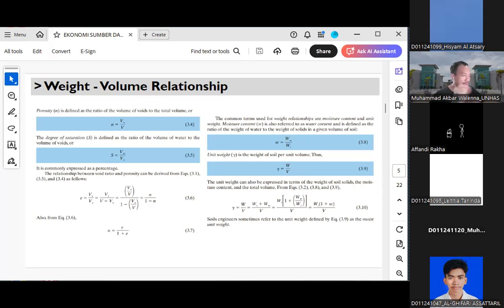Because we are adding up the water, also filling up the voids otherwise occupied by air. So basically, not only are they occupying more space, but they also add more weight, because it contains water. So here's the thing, it can contain more water, but when it comes to the volume, it doesn't change that much. So what really adds to the unit weight of saturated soil is the amount of water and the weight of water it carries.